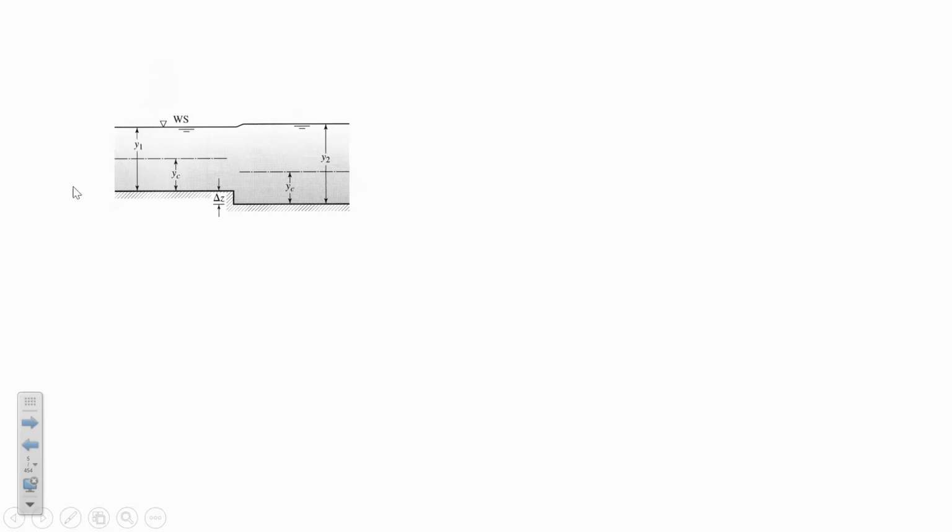So water is flowing down the river. This is a side view of flow through a channel, and the water encounters a step down. The question in this classic problem is, what will be the new depth if you have the water flowing and the depth upstream is greater than the critical depth? So you notice how Y1 is bigger than Yc? What does that tell us about the flow regime? Are conditions supercritical or subcritical at location 1?